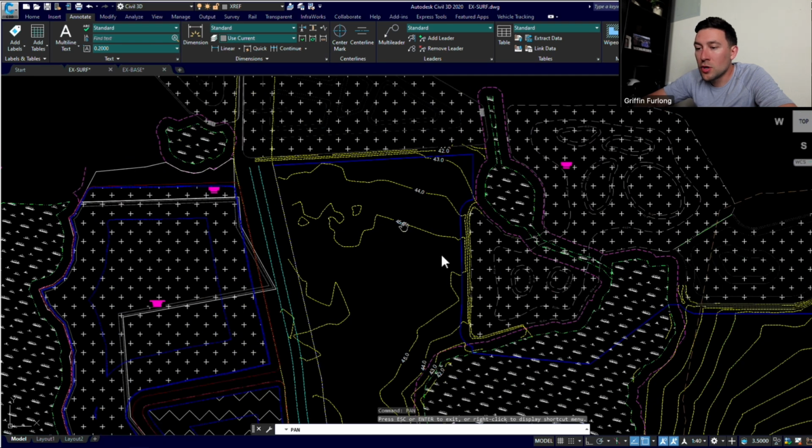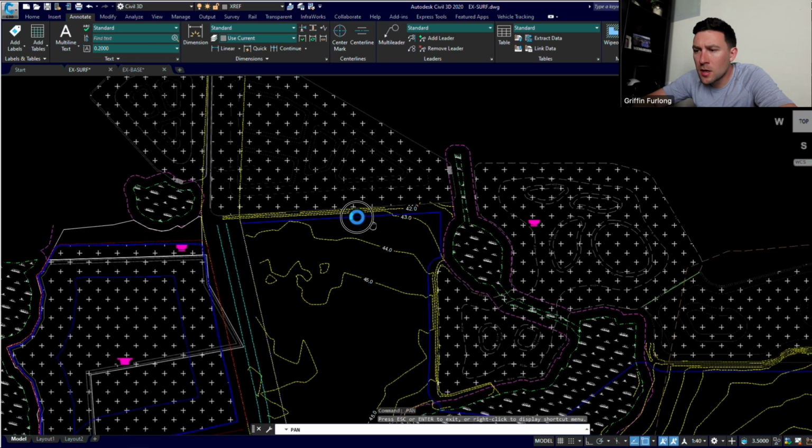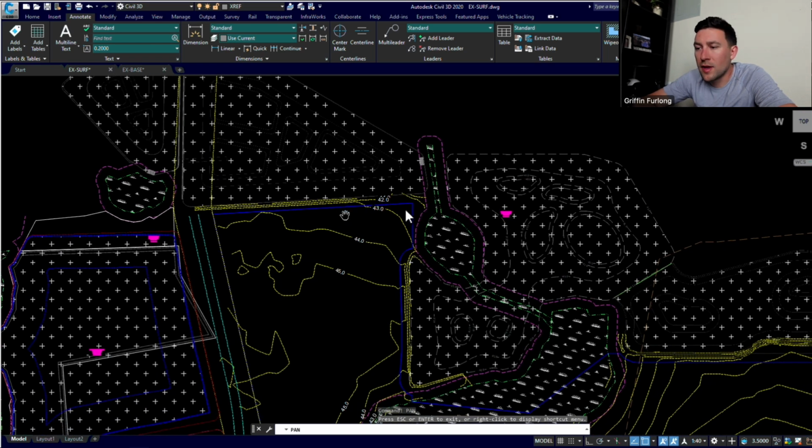So it looks like this water up here does not want to drain to this wetland. We have some sort of high point right here because I'm looking at this elevation of 45 here. And if I'm a water droplet, where do I want to go? Naturally, it looks like water wants to fall downhill over to this, I think it's a floodplain compensation area. We can look back at that survey and see what kind of information we got on this.